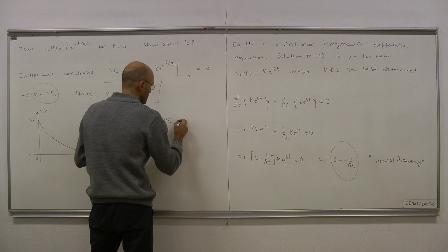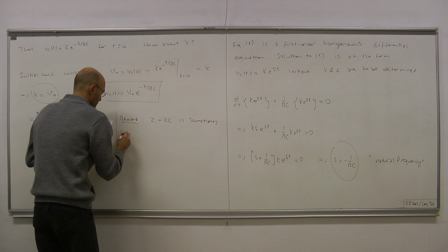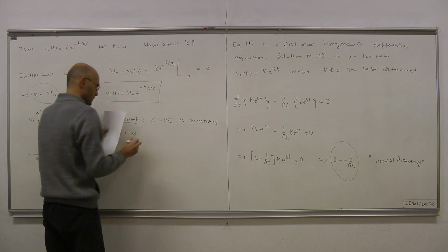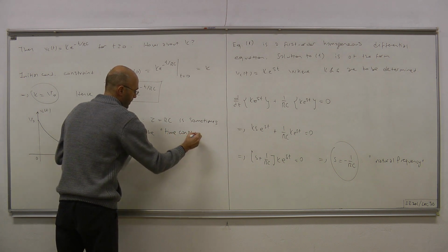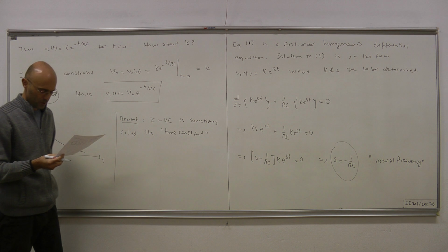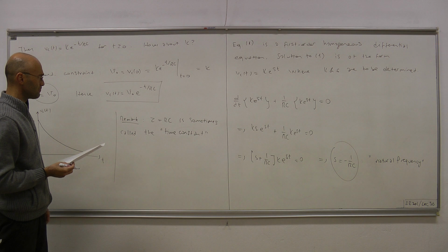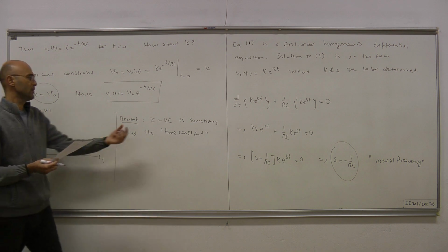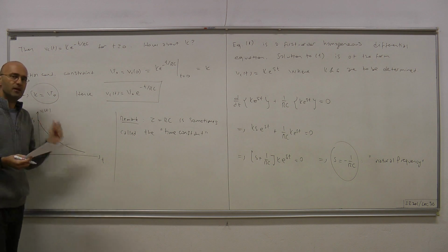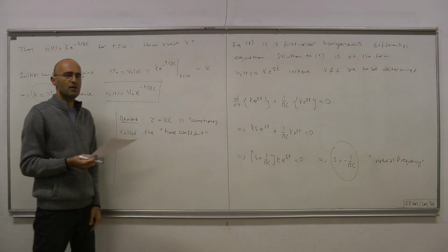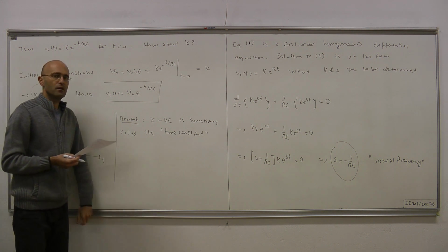Now the smaller the time constant, the faster the response. If it's very small, then this VC(t) becomes practically 0 in a very short amount of time. If, however, it's large, then it will be more sluggish to move toward 0.